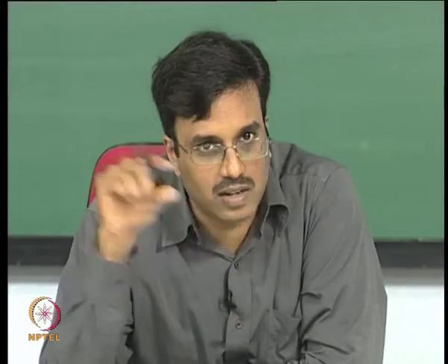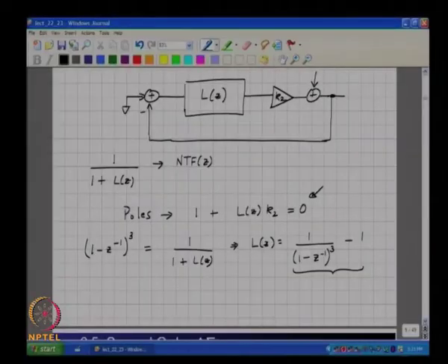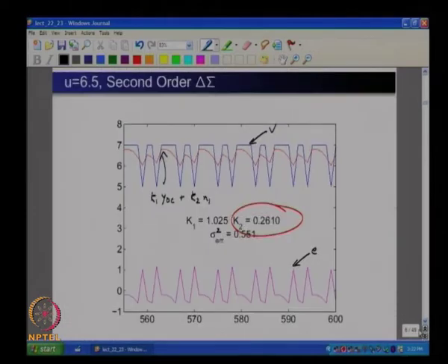It corresponds to the modulator being in that uniform staircase region, and as the input signal gets closer and closer to the saturation limit, K2 will fall. So we plot the locus of the poles of the system, which are the roots of 1 plus K2 times L of z, as K2 varies from 1 to 0, and I have done that experiment for you.